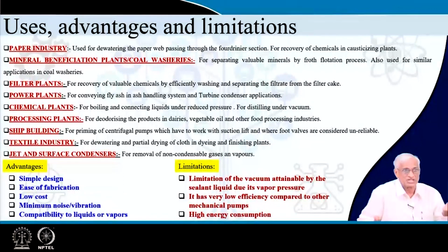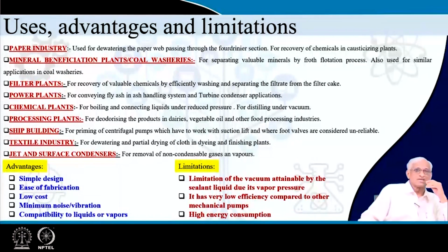Okay? So, you have to think of all these things when to use these pumps. Whatever is the energy you have, acceptable energy, or chemical compatibility, or whether water is allowed at all. In some applications, water vapor is not at all allowed. In such applications, you cannot use this. So, you have to take a judicious decision when to use these water ring pumps.